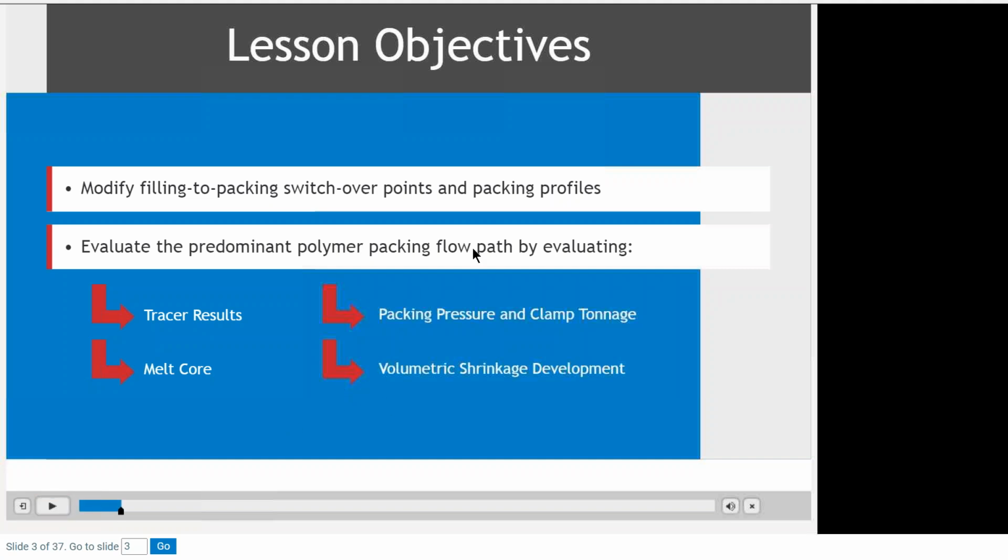That's very important. As I said, we will look at different pack pressures and what they actually will do inside the molded part during the packing phase. We'll take the tracer results. We'll see what they look like. They're massless particles. They float around in the molten material, and you really can use those to see what I call the flow behind the flow, the internal material flow based on the geometry of the material. This is really interesting to see.